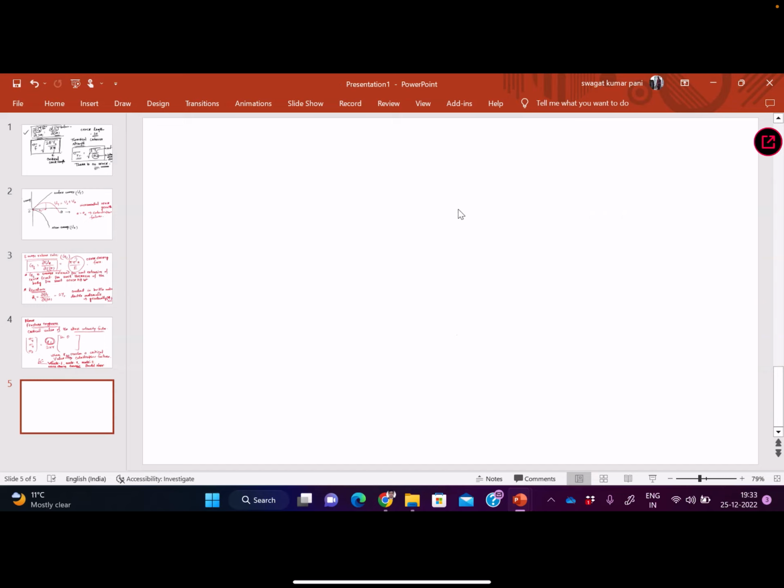So the important formulas that are relevant for GATE are: first, K1C = Y sigma root pi a. This Y is the geometric factor. For surface crack it is 1.12. For center crack it is 1. That's why surface crack is more severe.